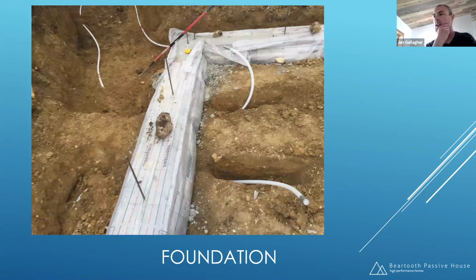Okay, so here's something. I mentioned that geothermal preheat in the ventilation piece of it. That was that gray box. And I mentioned that it was connected to tubes that were buried in the ground. So these are those tubes. We buried 300 foot of 1-inch PEX that went around the foundation. And then we had a big trench that we dug like 75 feet or so out into the field. So these tubes end up connecting to that box. That box has a pump in it.